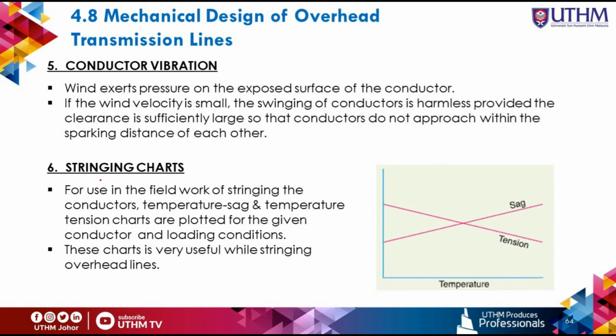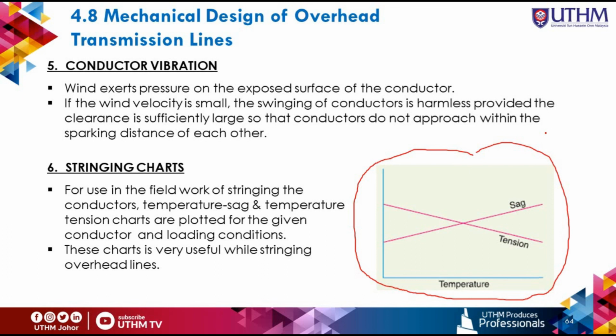For use in the fieldwork of stringing, the conductor's temperature sag and temperature tension charts are plotted for the given conductor and loading conditions. Such curves are called stringing charts. This figure shows the stringing charts. This chart is very useful while stringing overhead lines. For example, on a hot sunny day, the temperature will be increased.